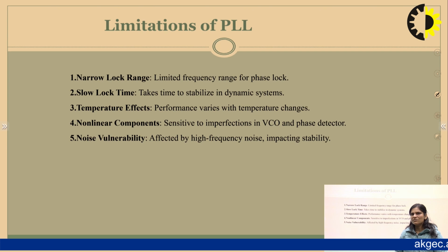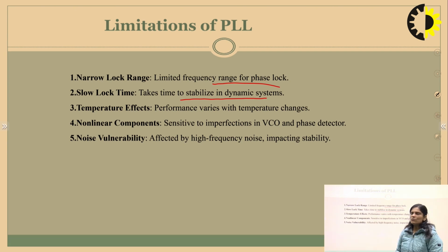Now the limitations of PLL. First one is narrow lock range: limited frequency range for phase lock. Second is slow lock time: it takes time to stabilize in dynamic systems. Third is temperature effects: the performance varies with temperature changes. Fourth one is non-linear components: it is sensitive to imperfections in the VCO and phase detector. The last one is noise vulnerability: affected by high frequency noise, impacting stability. So these are the limitations of phase locked loop.